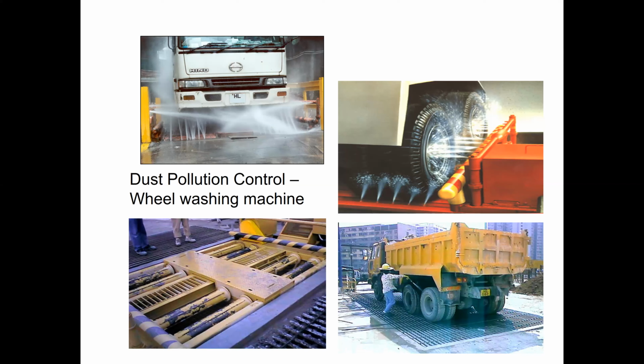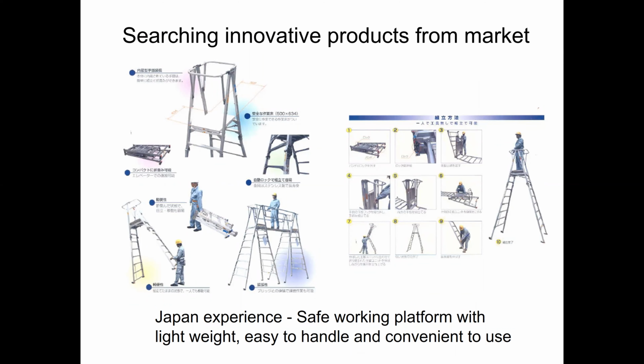At the workplace, we are going to share good safety practices, and this is another innovative product: a safe working platform. They are made from aluminium, lightweight, adjustable and convenient to use. You can make these platforms go up and down as a working platform for plastering under the roof, brickwork or anything. Different kinds of platforms are available, made of aluminium. We should also use these kinds of lightweight working platforms. They have a proper platform with a toe board, so they are safe for people.